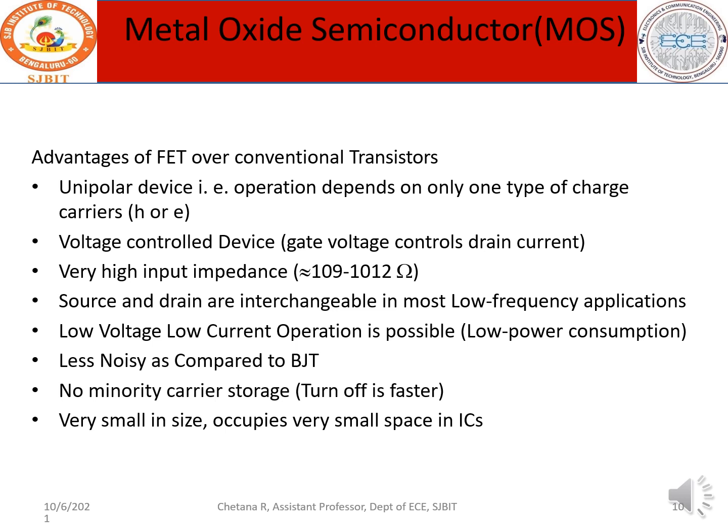Metal oxide semiconductor advantages. What are the advantages of FET over BJT? FET is a unipolar device. So there is only one type of charge carrier present, the majority charge carrier. Either the current conduction happens because of the holes or the electrons. Whereas in BJT, both holes and electrons will be conducting. They are bipolar devices. So that is one of the differences between BJT and FET.